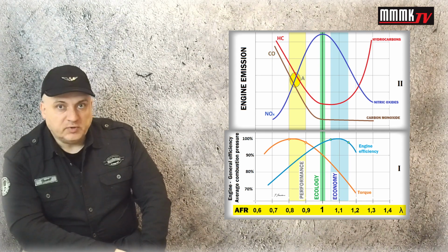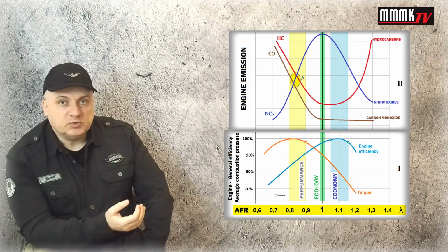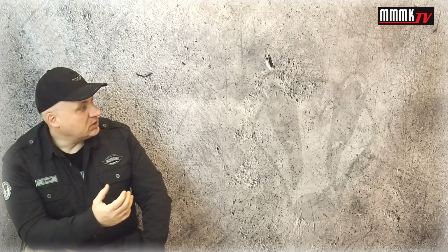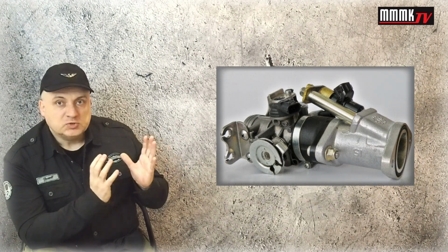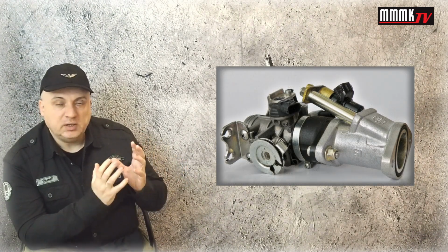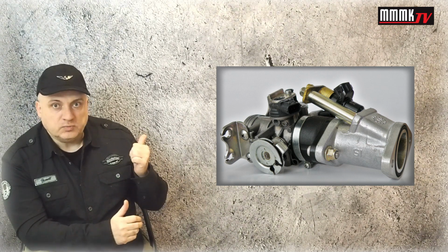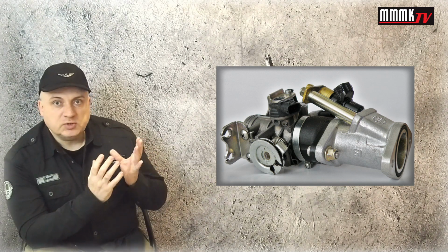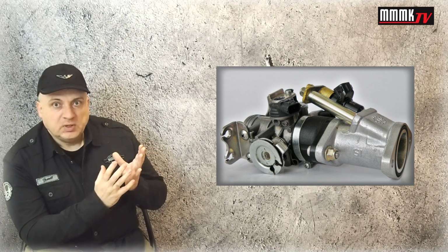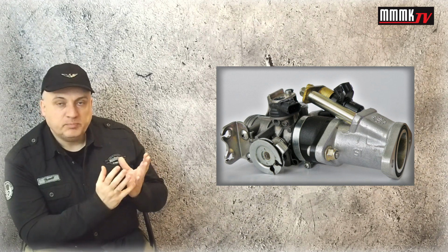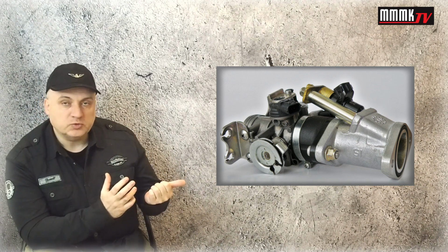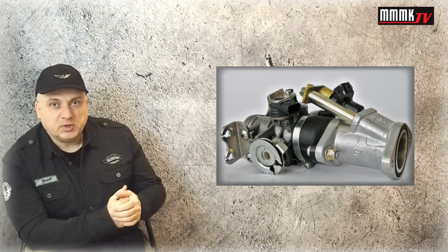That had to be verified. And then going deeper into the details, I found out that the injection system itself is exactly identical, the one for the domestic market and the one for the European market, for instance. So there are no differences in any components. The only difference is the ECU, and of course the ECU also looks identical. It even has the same part number, the one for Euro 3 and the one for the domestic market.